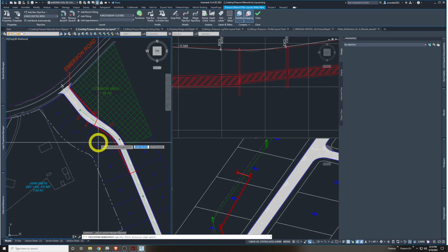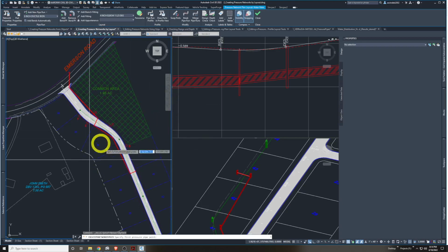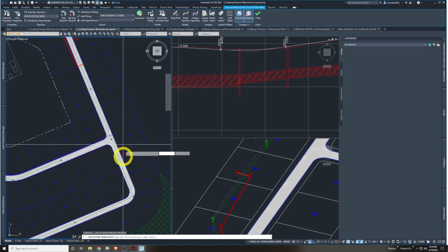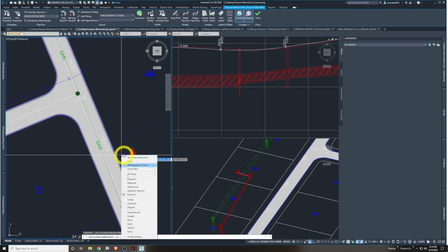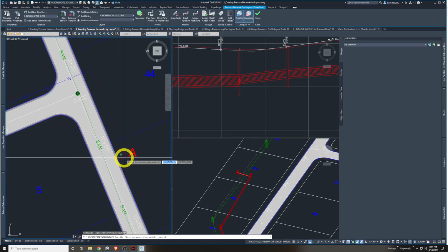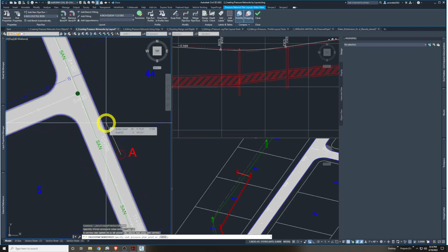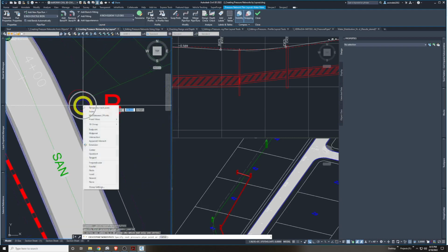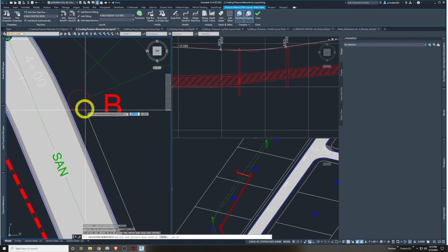Let's go back to the beginning. I somehow lost this the first time around. Now we have all of our options, but my initial option here, my heads up prompt, is specify first pressure pipe point, which is great. Let's start back at the circle, center, start, okay. And then we'll simply snap to circle B where we want the next spot, center.